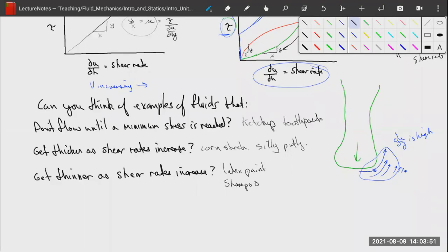So these polymer chains get very entangled, right? And then if you try to shear them like this, they get knotted almost. Like if you push them really fast, they stick to each other hard, they get all tangled up. It's just like if you were taking a bunch of Christmas lights out of a box and tried to pull them apart really fast, right? They're going to get stuck. So long chained fluids or solutions like cornstarch will be shear thickening, right?